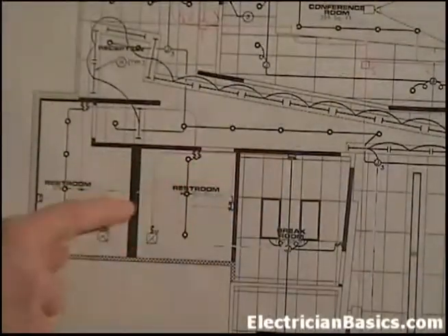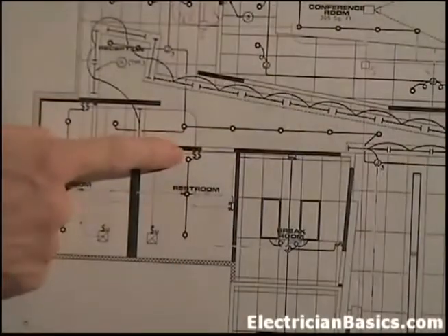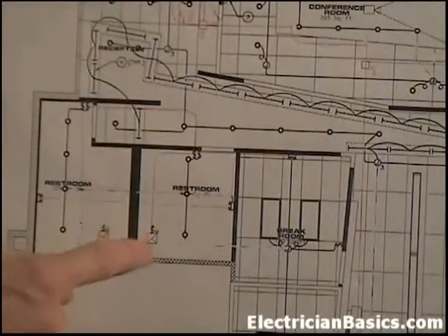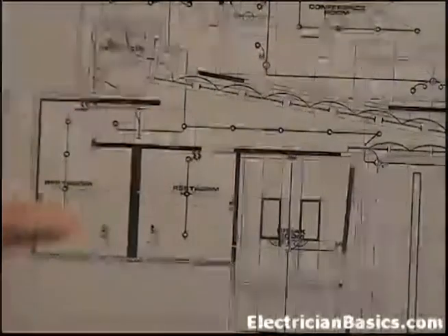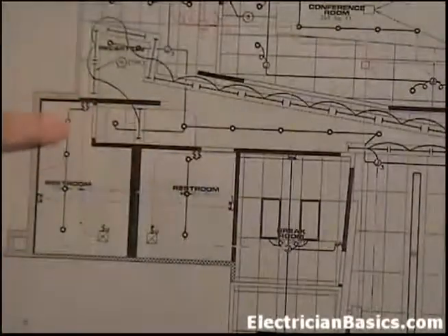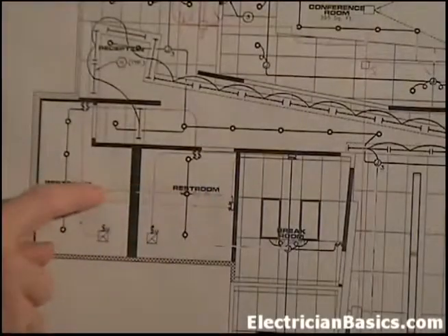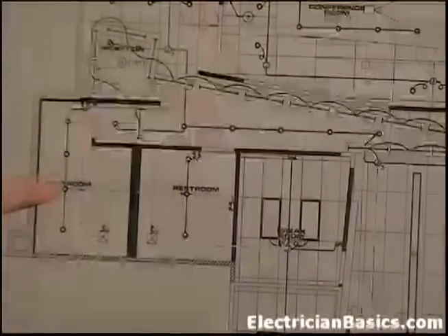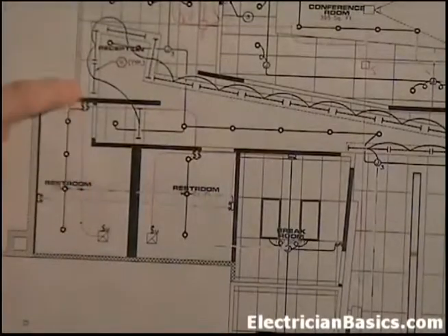Now that we're here at the switch, we keep this part of it the same, where the switch powers the lights, and then one comes off on the same circuit for the fan. And the same thing was done here. Here's our conduit to the fan, and then here is the one for the lights. Originally they had conduit coming across through here to get the power over here into the switch, but we didn't want to run our power through all of these lights. We wanted to run it to the switch first and then through the lights.